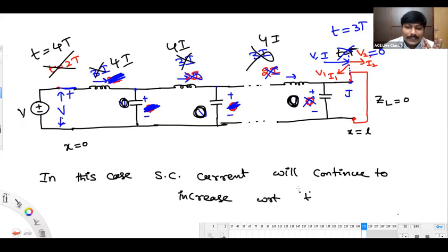Following all of you? Please tell me, in the open circuit line case as well as the short circuit line case, we have discussed almost 4 propagations now. What is the highest voltage experienced by the transmission line in any propagation? That will be 2V. So I can say now, that is the maximum switching over voltage.